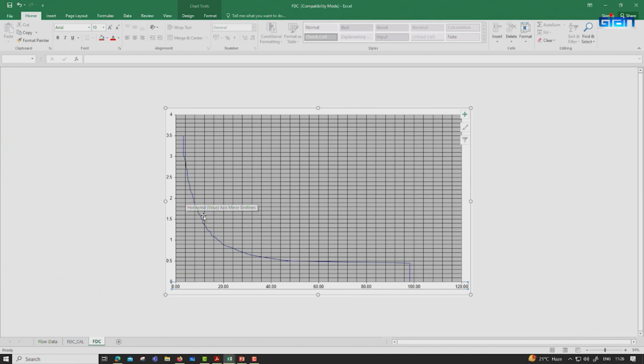And therefore, the decision on the selection from the flow duration curve will depend upon how much tariff you are getting. If you are getting a very high tariff, you can even go for 2 cubic meters per second and have a very big plant. It can run only a few days, maybe 20-30 days on full load, but you can afford the higher capacity and larger plant because your tariff is high.